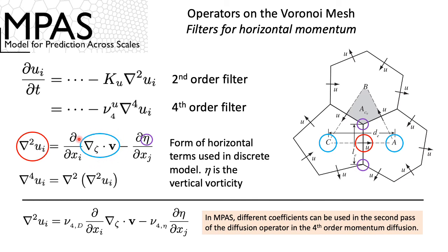Here you see the blue circle. That's that velocity divergence. That divergence is essentially the normal velocity integrated around the edges, multiplied by the length times that velocity for each edge, summed, then divided by the area. It looks like a mass flux divergence, only in this case it's a velocity divergence, same thing.